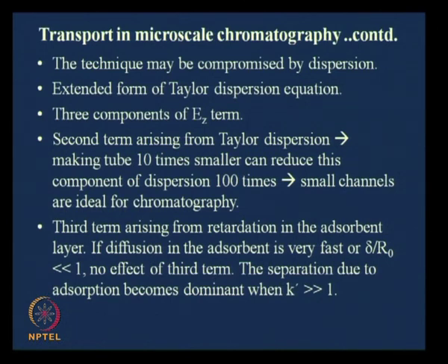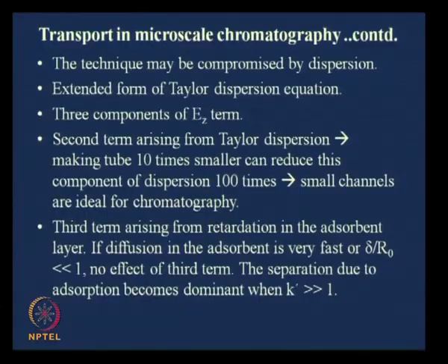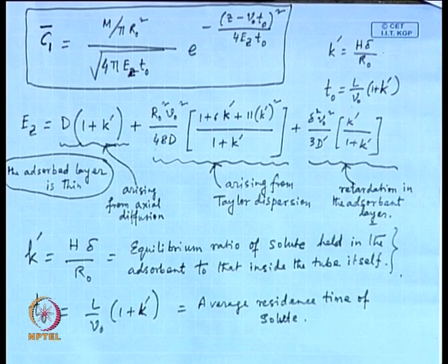Of course, you cannot make this small endlessly, because you will encounter a very high pressure drop in that case. As you make it smaller, but at least from the dispersion point of view, smaller is the better. The third term is arising from retardation in the adsorbent layer, that you have already pointed out.